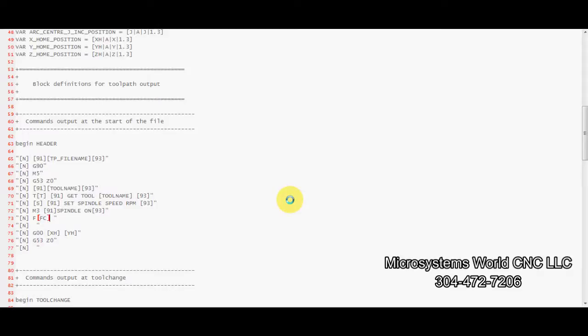That means feed rate for cutting, XY. And what I did there was I set a feed rate for X and Y at the feed rate set in Aspire or VCarve for the XY tools.